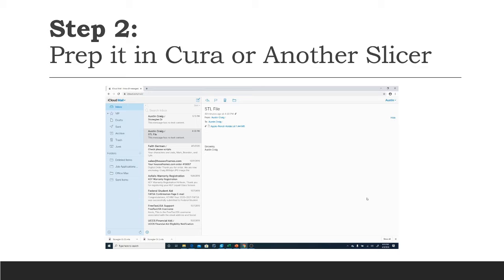Now when you originally open Cura, support is going to be turned off. Now you're going to really want it to be turned on for our case, so make sure that little check mark is there. And it'll be there in just a second. Computer's lagging behind, and there it is. Now it's pretty much perfect. So what we're going to have to do is hit the slice button down here. It'll completely slice it for us.